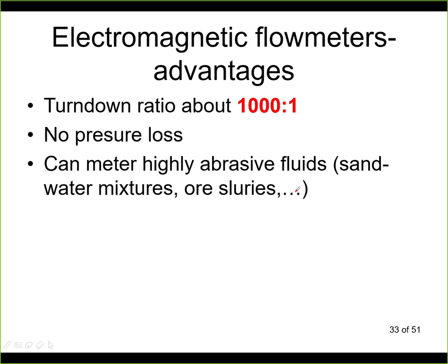Now there is no pressure loss, or very small pressure loss, and it can also measure highly abrasive liquids. So for example, sand-water mixtures, or slurries, and so on. So here it's not sensitive to those effects, to abrasion, to bubbles, and so on.